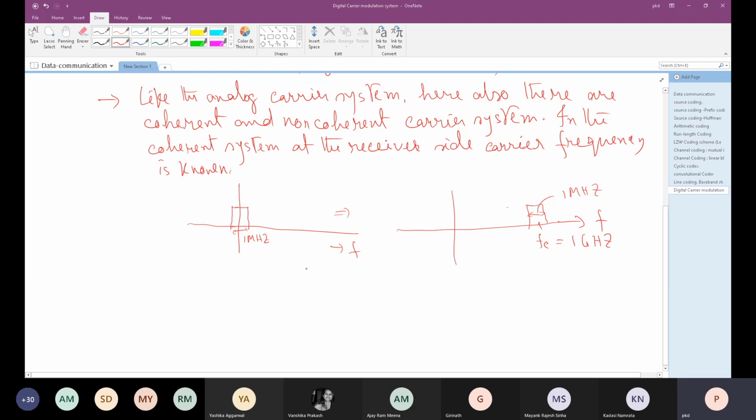So generally, if we take the power spectrum of the carrier modulation, then we have one band at F plus Fc and another at F minus Fc. So around the Fc there will be two such basebands generated. That could be shown easily by simple manipulation of the Fourier transforms.